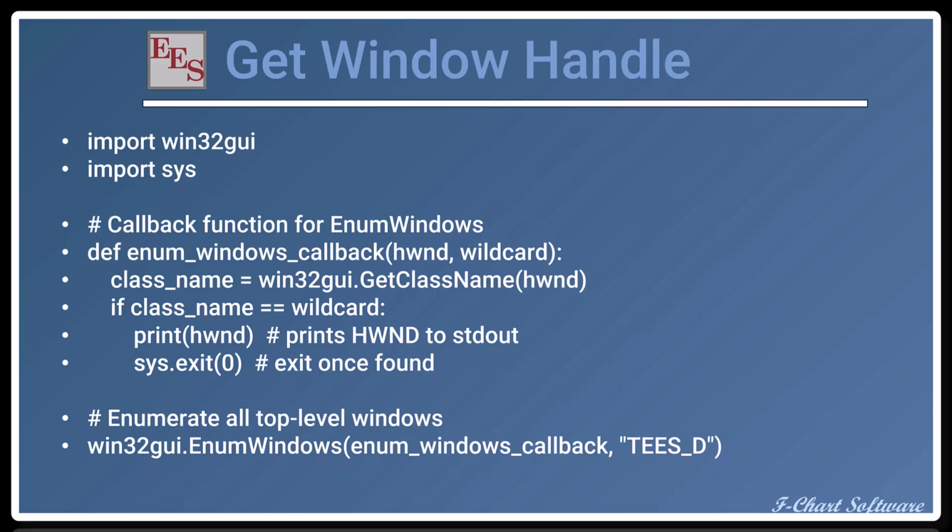But otherwise, the approach used from within LabVIEW is exactly the same as what we've seen previously to communicate with EES from other programs. We're going to keep EES open and ready to respond to commands issued by the calling program, and we're going to pass data to and from EES using data files, and the whole process then becomes relatively fast because EES never has to restart before it executes a command.